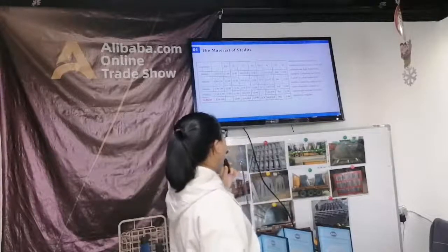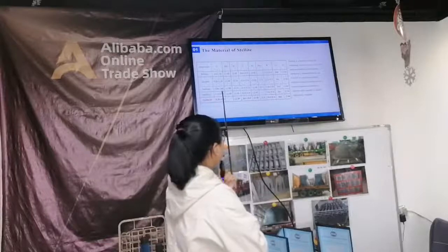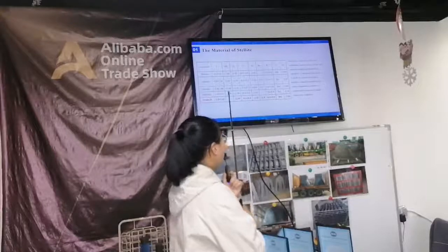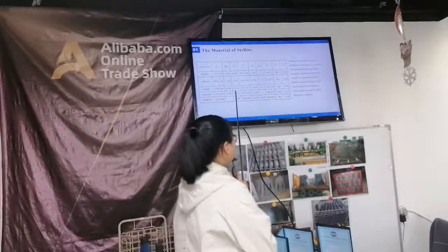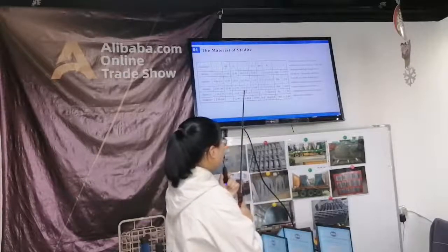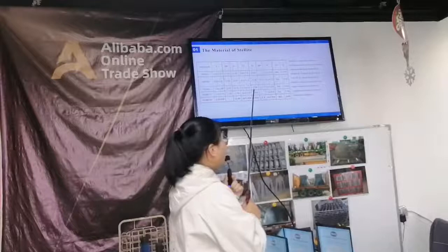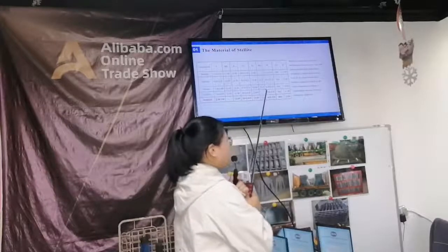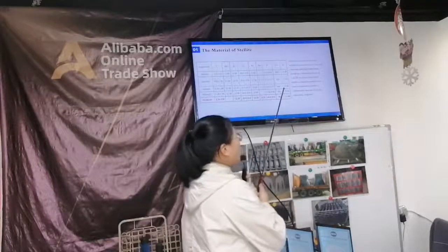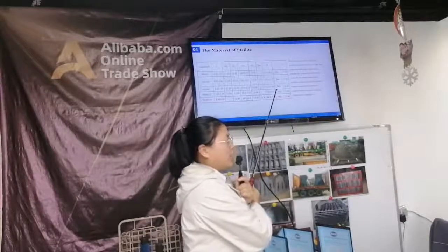Stellite 6: carbon is 0.9 to 1.4%. Manganese is less than 1.0%. Silicon is less than 1.5%. Chromium is 27 to 31%. Nickel is 3.0%. Tungsten is 3.5 to 5.5%. Iron is less than 3.0%, and the cobalt is balanced.